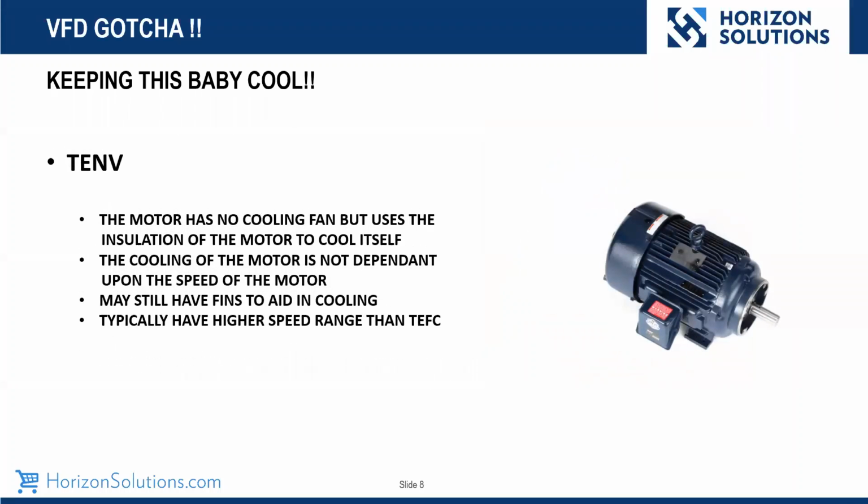Another way to do this is called totally enclosed non-ventilated, or TENV. The motor, in this case, has no cooling fan at all, but uses the insulation of the motor to cool itself. Again, the cooling of the motor is not dependent upon the speed of the motor, but the motor may still have fins to aid in the cooling. Now, the motor you see here is a Marathon Blue Max motor, which is an inverter duty motor, designed to go with a VFD, and it has fins, even though there's no fan on this. The fins aid in the cooling.